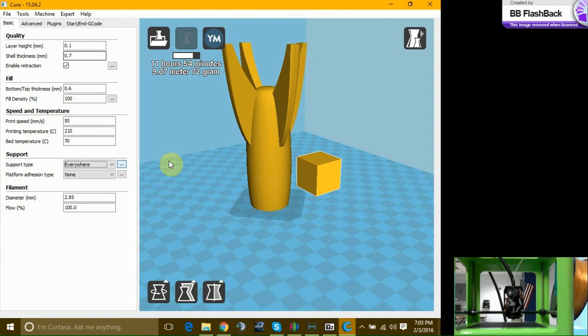I worked with an Ultimaker at the Hack Lab in Boynton Beach, and I printed out a couple parts, and I was saying, wow, this isn't fitting. So I took 0.003 of an inch off, and then things fit perfectly, spot on. Travis, do you remember that? It was pretty cool.